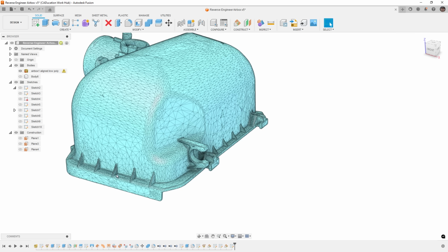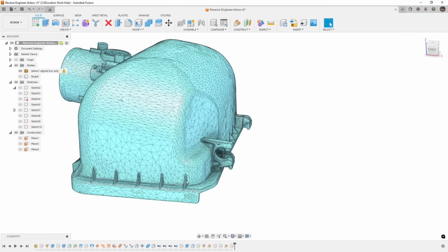Then in areas where it's thicker, like in the corner, if we just do a chamfer, we can just have infill in that area and it's not going to be solid. Whereas these kinds of features take a lot more effort to 3D print, and they're not really going to be that strong just based on the print orientation, where a large chamfer is probably a better option for a 3D printed part.